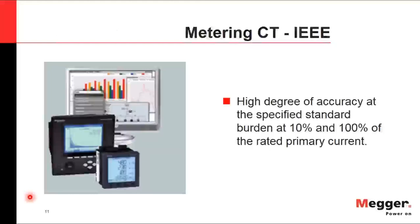If we start looking into metering type CTs according to IEEE, there's a high degree of accuracy at the specified standard burden at 10% and 100% of the rated primary current. So what we're looking at is very specific and accurate measurement of current, and the transformation that we have from primary to secondary has to be extremely accurate.